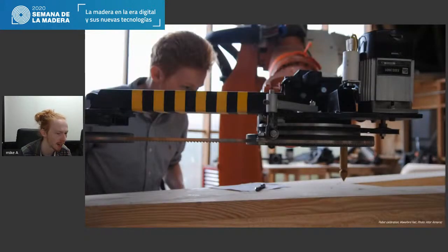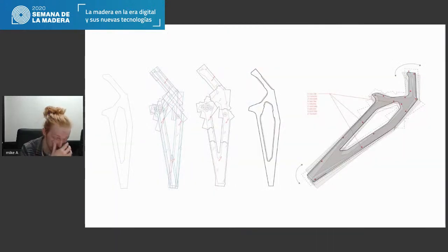So we fell back to the original idea of a carpenter marking faces. Inspired by this, we came up with a system where we created a set of CNC machined templates, which we used to define the glulam positioning. We also used these to transfer the distinct positions that we needed to reference where the frame would be for the robot, and also where the flitch plate connections and any shear joint connections could be located by hand.